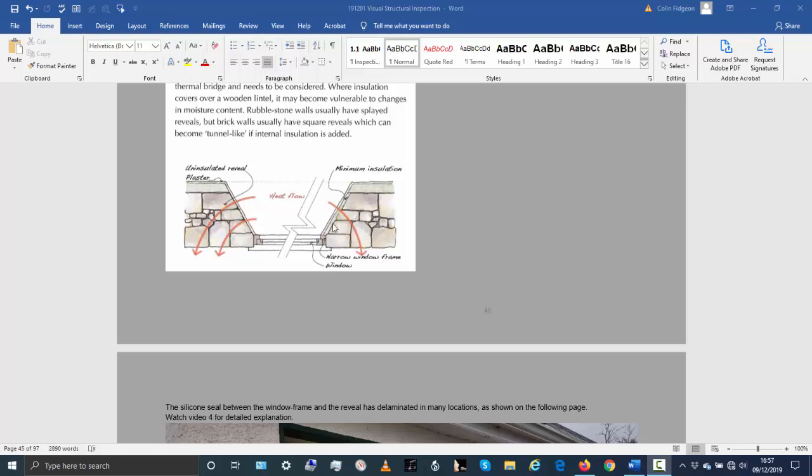So the problem might have resulted from condensation forming on the walls, from hot moist air hitting a cold, relatively uninsulated surface, leading to black mold. So that's one possible cause.